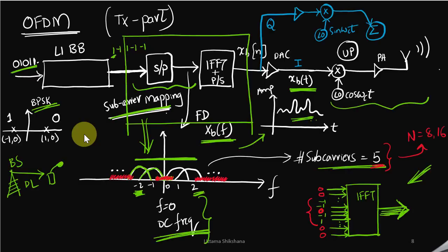All right. So first, I will start with a glimpse of what we had discussed in the previous video, especially in the downlink part. In case of OFDM system, I was mentioning that there are two new blocks which are introduced and which are important for us to discuss this concept. One is subcarrier mapping and another one is IFFT, right? To overcome the effects of LO leakage in subcarrier mapping for our baseband signal in the frequency domain, I was mentioning that the DC should be made 0.